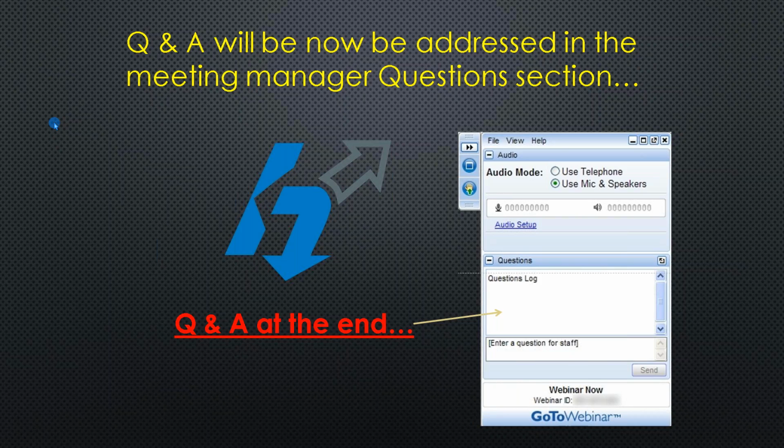And once you start refining your mesh, what you're doing is building confidence that, okay, we're looking for the right mesh size. Two, we're looking to make sure that just increasing or decreasing the element count has little to no effect on the results. You want to run multiple tests and see little to no change from test to test to test. That's your proof.